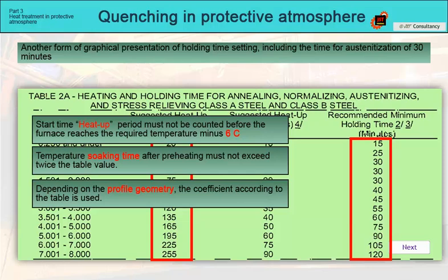Each heat treatment facility has a different approach to this problem based on long-term experience and evaluation of heat treatment results. However, all of these methods are empirical and cannot fully replace measurements of T-surface and T-core directly placed in the batch. However, for repeated processes, they can be set accurately enough to ensure that the heat treatment is carried out in accordance with standards and requirements and meets reproducibility and reliability.